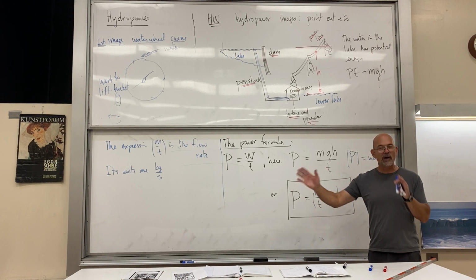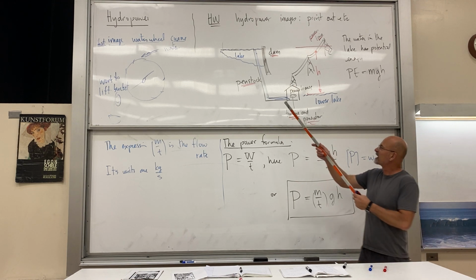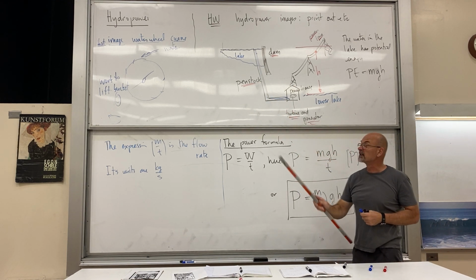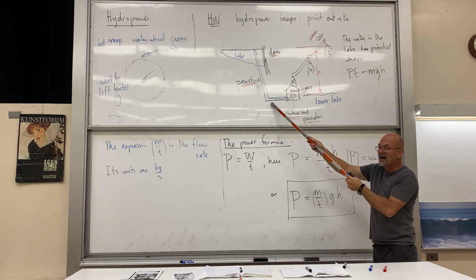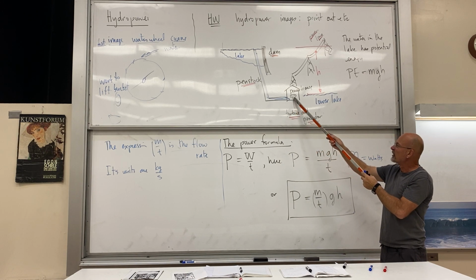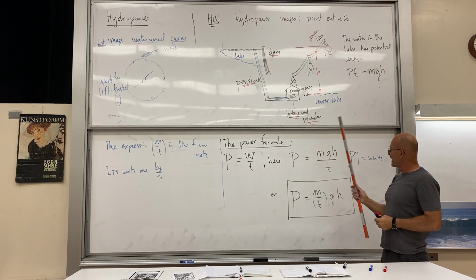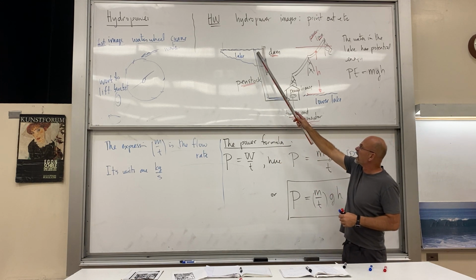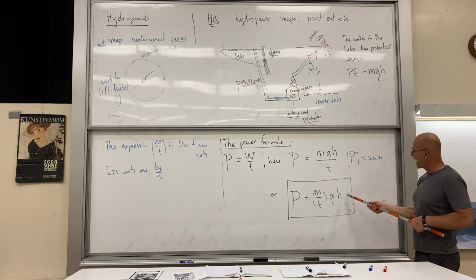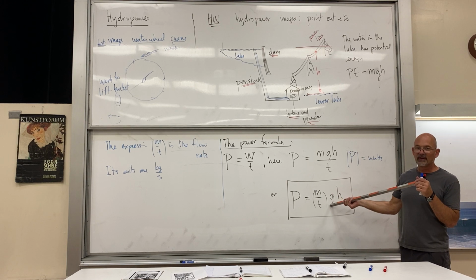The wattage, the power output of a power plant, can be controlled. g and h are basically fixed. Sure, the lake can run down a bit, but in the power plants we're going to talk about mostly, the penstock is really long. It's a long pipe that goes way down a mountainside, so the powerhouse is far away from the actual dam. We're going to ignore the fact that the lake could run down in the dry season, and just take the top of the lake down to the lower lake, and that's the h. So that's a fixed quantity. g is gravity, so that's also fixed.